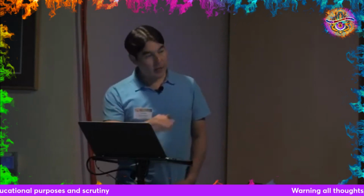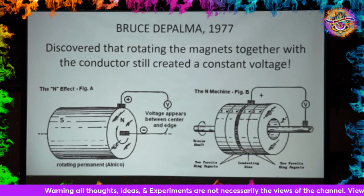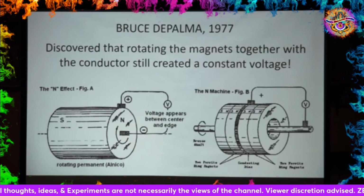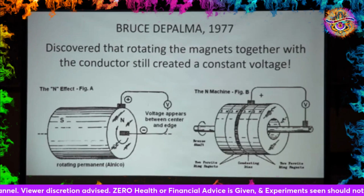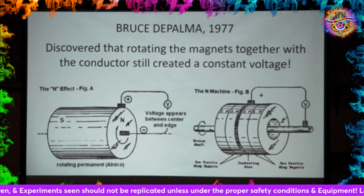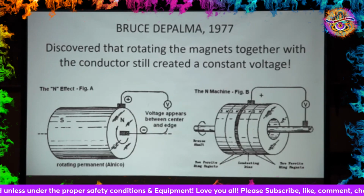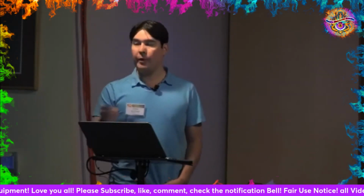And so the second image, in figure B, is basically two sets of magnets on either side of a conductor. That thing going down the middle is basically a copper disc, or it could be brass or any type of non-ferrous, non-magnetic metal being used as a conductor. And the same thing, if you have a shaft running through there and you rotate that, you find the same thing. You get a voltage potential difference between the perimeter and the shaft. But again, in any of these configurations, they're always going to show current but virtually no voltage.